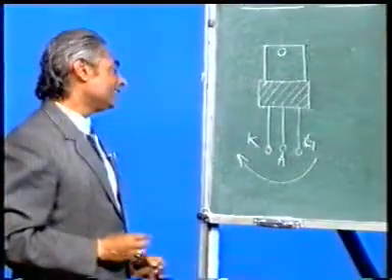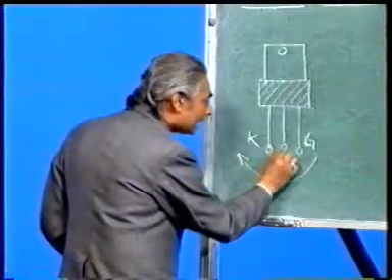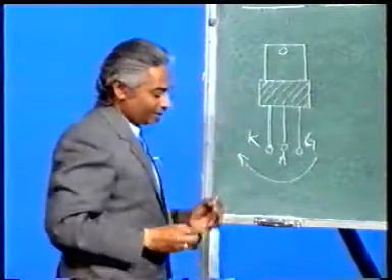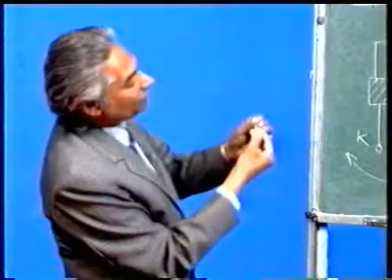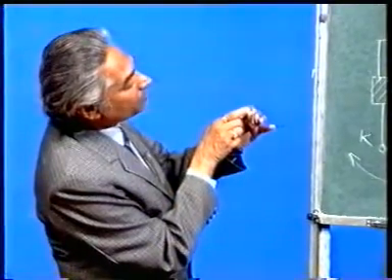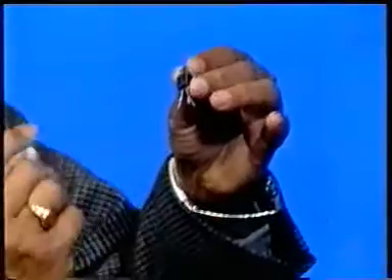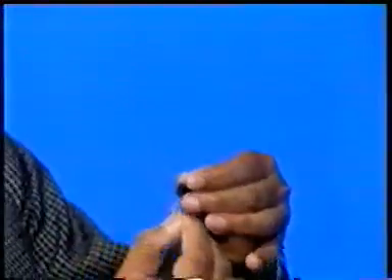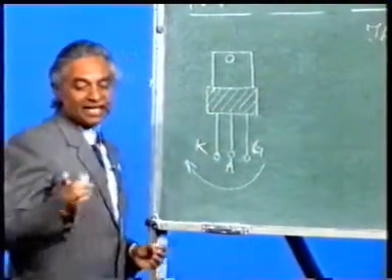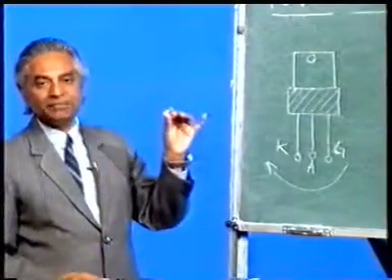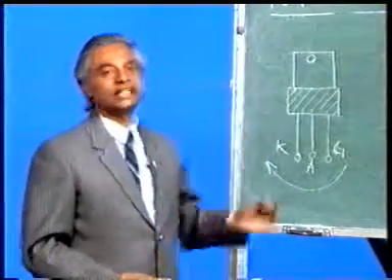Now, again there is a check that this anode has to be the body. So, if I test between the middle terminal, which is anode, and the body, which is this metal portion, the multimeter will show continuity. So, these are the methods for metallic pack and for plastic pack to know the terminals of an SCR.